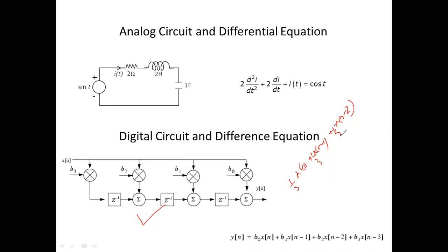See here, I am manipulating digital data, right? The discrete data: this semester, previous semester, semester previous to that. And what you are doing is giving a delay, right? Current semester, previous semester, and semester previous to that. So this particular operation, the moving average, can be represented using a digital circuit, where these elements here